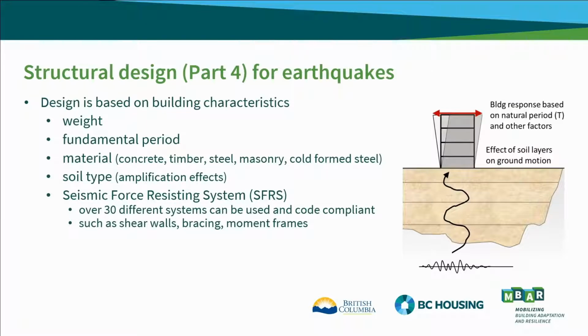So a few aspects about design of new buildings. The design is based on the building's weight, its fundamental period. There's 5 different material types, and it includes the amplification due to different soils.